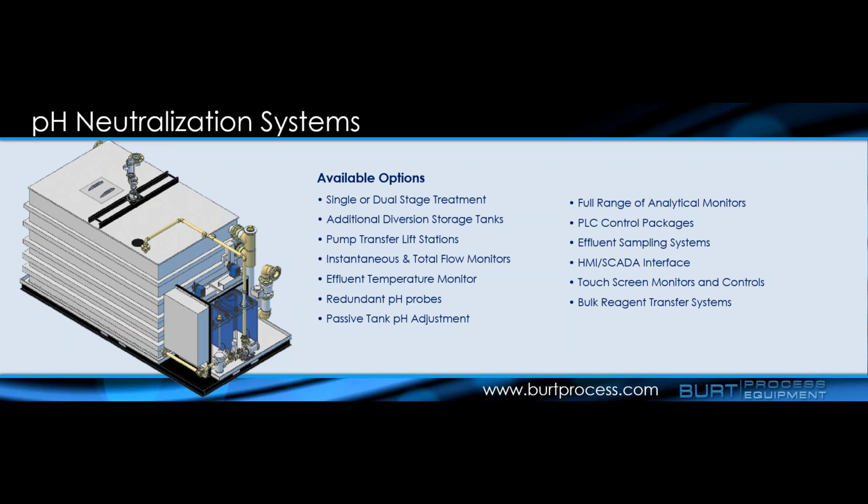Redundant pH probes. Redundancy in pH probes is generally done with 3 pH probes as opposed to 2. The ability to use 3 allows you to have a reference probe to compare the other 2 probes to, so you can end up with a comparison. So if you have one probe which is reading 5, one probe is reading 9, then your comparison probe is reading, say, 9, you know obviously which probe is bad, as opposed to having some different probes available.